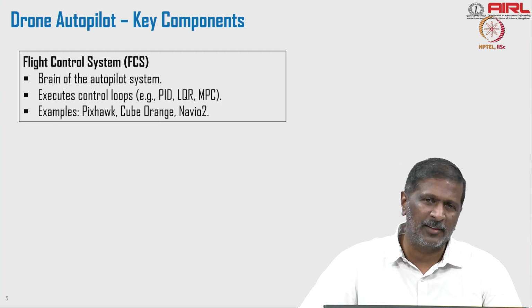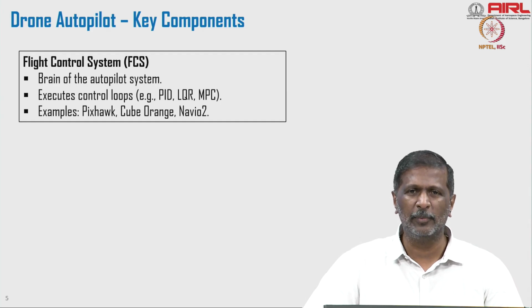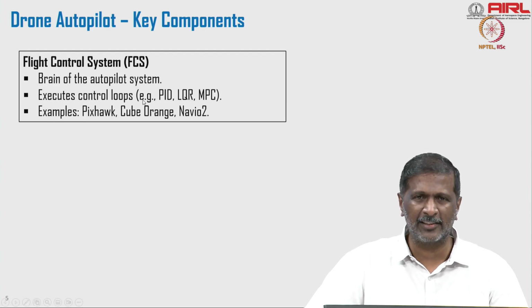I converted the mission requirement to a functional technical requirement. Basically going to a specific altitude, H, at a rate at which I want to climb, 2 meters per second, which is going to be comfortable. Then I'm giving a vertical speed command of 2 meters per second. So you climb from the ground and reach that particular altitude. When you reach the altitude, you stop and you maintain that altitude. If you decrease, you give more thrust. If you go up, reduce the thrust so that you maintain the same altitude, right? So that's where these commands will take care.